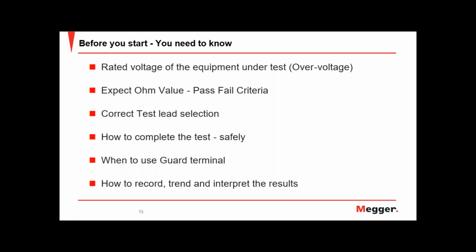out. We also need to know how to test safely. So we need to know how to de-energize, how to lock off, to prove dead, and obviously to earth or ground out before we connect our test leads. We then perform our tests, and then we would earth or ground out again before we disconnect our test leads.